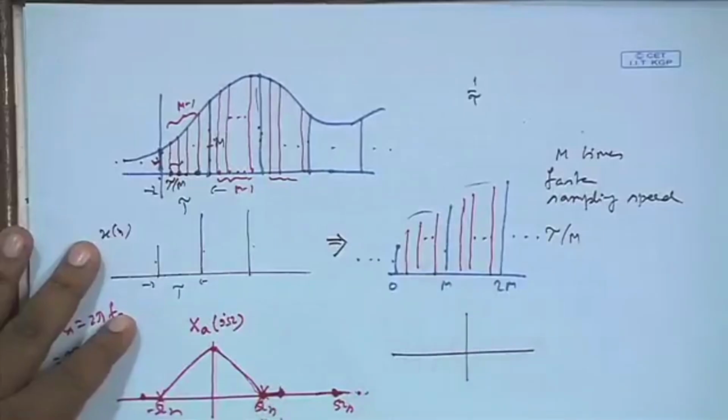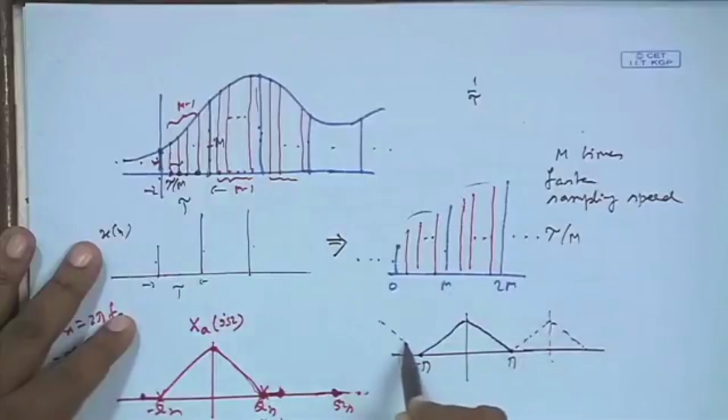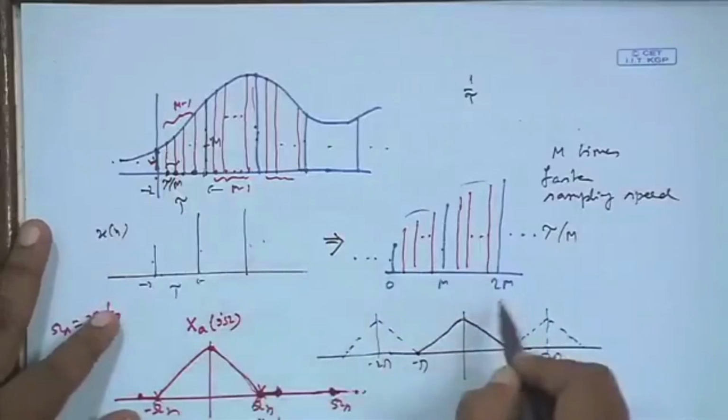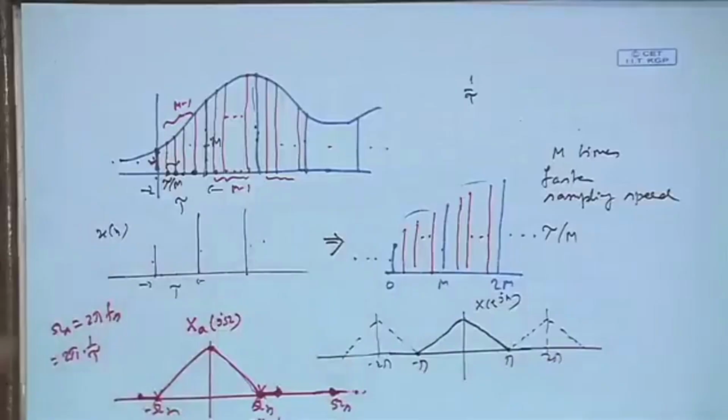Half the sampling frequency always goes to pi and minus pi, but since half the sampling frequency is the same as the band limiting frequency, the band limiting frequency also goes to pi and minus pi, and then there will be periodic repetition, dot dot dot. That is the DTFT of x e to the power j omega, where x n is this low sampling rate sequence.